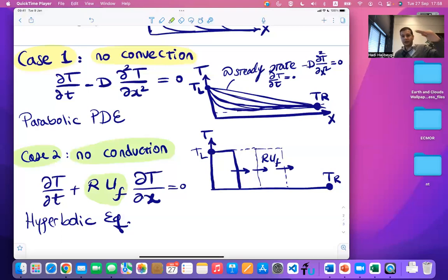So convective heat transfer is a hyperbolic problem that is having sudden change. Imagine you have hot fluid coming with the velocity rho u_f through your medium. If you are standing here, you have no understanding of this type of heat flux until the carrier comes to you and you understand there is a hot fluid flowing through this porous material. Imagine someone has thrown water on you and you have no idea until it just reaches you. So that's the wave equation, or hyperbolic problems.